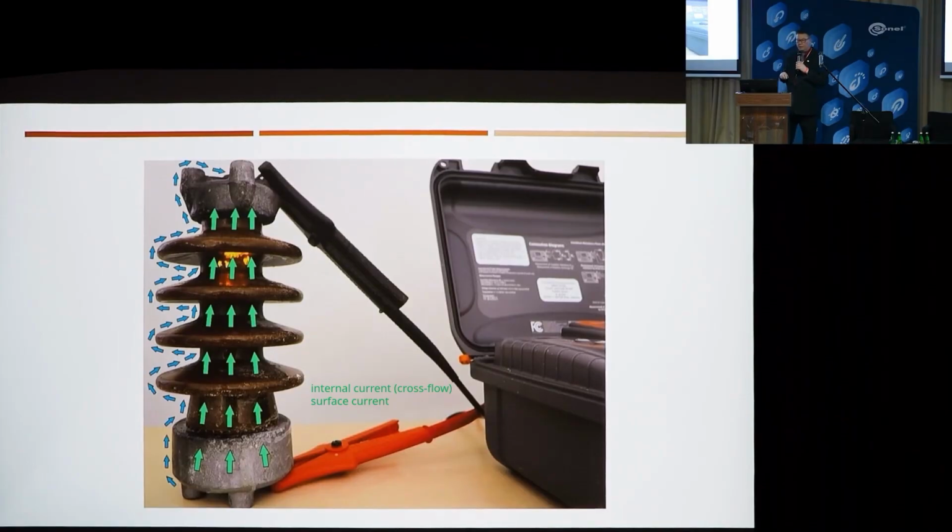As I already mentioned, the currents we're measuring are very small. And current will always choose the path of lower resistance, right? Let's take as an example the insulator we can see here. When measuring insulation resistance in the traditional two-wire way, we won't be measuring just the insulation resistance of this object.